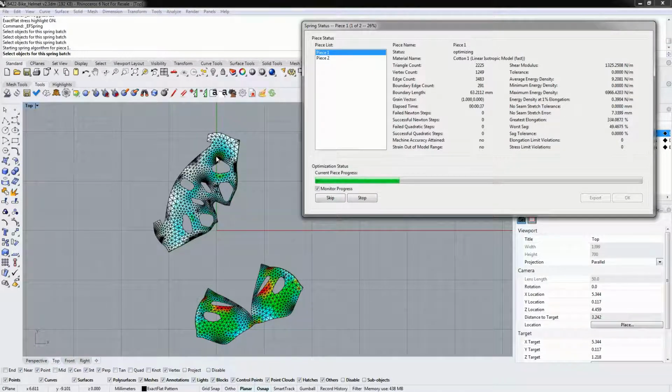We may also have problems with the optimizer because of the shape and the cuts that have been created. If we're trying to optimize extremely complex curved objects with extreme complex curvature, double curvature, very, very wavy, the optimizer may not be able to fully resolve it. In that case, you may want to look at splitting up your mesh to allow the shape to be optimized better.